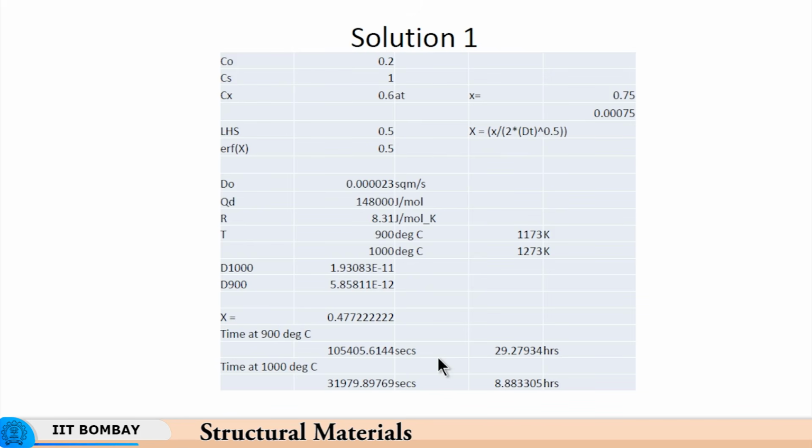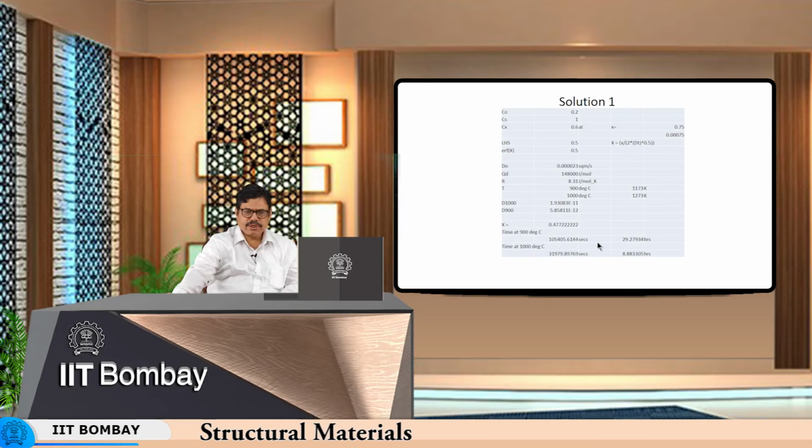For example, the volume expansion, the rate of volume expansion. So if we are to take care of those issues, then a relatively slower heat treatment may be better in terms of the ductility of the material when we finish the carburization and we quench the material. So basically what it means is the volume changes or dimensional changes after cooling can induce a lot of stresses in the material, and therefore if you have finished the heat treatment very quickly and you are quenching it from a relatively higher temperature, the volume changes and the dimensional changes will occur that much more rapidly and to a greater magnitude, because quenching from a high temperature will result in a higher dimensional change, and it can induce stresses in the